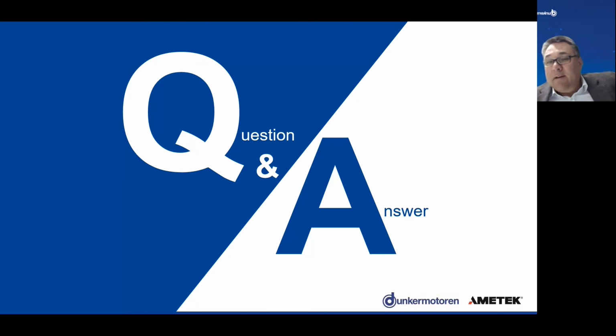Hello, Matthias. This is Jean-Philippe. Hello. Regarding the safety functionality, are all the drivers from MicroDrive integrated with all the safety functions? Is it standard, or do you need to ask for a specific safety function? No, when the motor comes with the integrated controller from Siemens, the IQ encoder, and it is the F version of the control unit from the PDC controllers from Siemens, then all the safety functions are enabled.